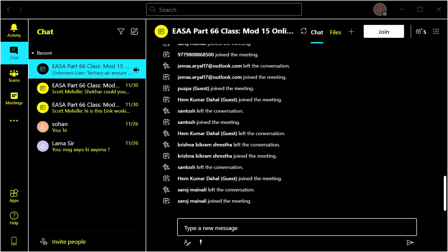And we use it as a form of preventative maintenance, where these will be taken out every so many hours, and if everything's fine, they'll just get changed every time. If we start to see a buildup of debris that's getting a bit more and more each time, we'll reduce the amount of hours between inspections. So, for example, on the aircraft I used to work on, one of these would come out every 36 hours. If we saw a buildup of debris, we'd change it down to 18 hours, so it'd come out a bit quicker. If it was getting worse again, we'd take it down to maybe 10 hours and 5 hours, and eventually say, no, that's enough now. We need to pull the engine. That bearing is breaking down far too much.